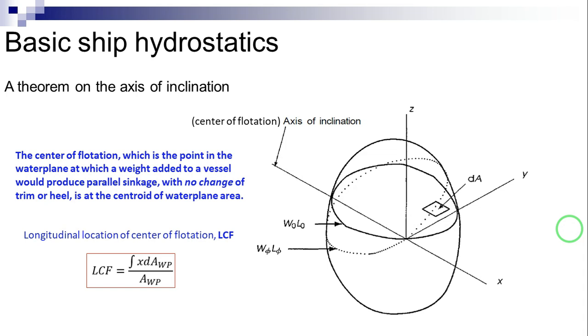The property also holds for larger heel angles if the floating body is wall-sided. This is the name given to floating bodies whose surface includes a cylinder in the broader geometrical sense with generators perpendicular to the initial water plane.